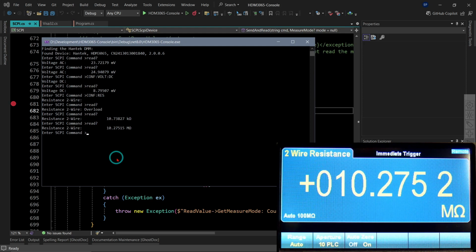Now these digital multimeters, the expensive ones like this 6.5 digit one, can usually read resistance and voltage and current, the common things. Normally they're hooked into test circuits, and they can be automated with software like LabVIEW and so on. You can write whole scripts, and they are very accurate in those 3 modes, but capacitance and frequency and so on is not something you normally use them for.